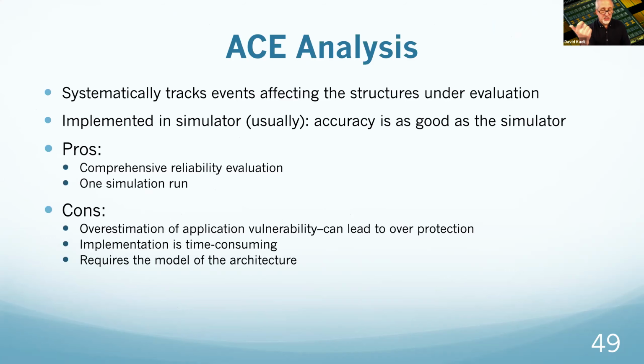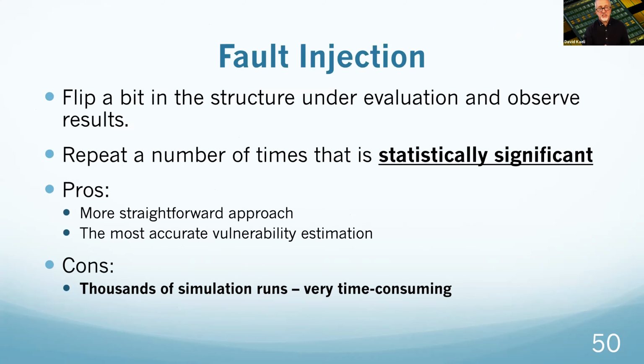The implementation is extremely time consuming, as I can vouch for through the thesis of Vilas Sridharan, and requires a model of the architecture. Fault injection is basically flipping a bit in a structure under evaluation and then observing the results. You repeat that a statistically significant number of times, and so it's very straightforward, it's very accurate, but it takes thousands of simulation runs and is very, very time consuming.